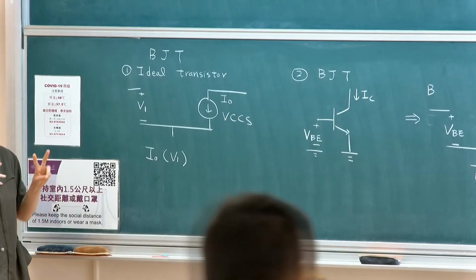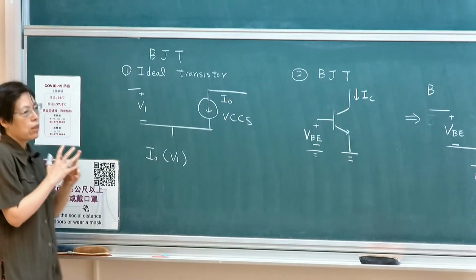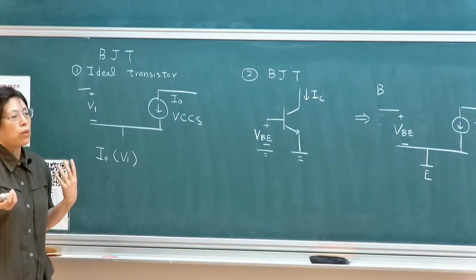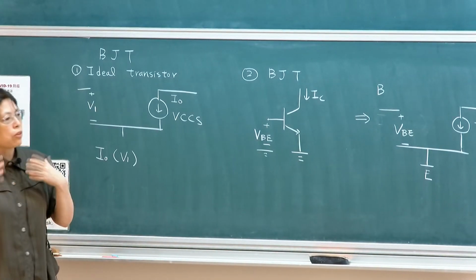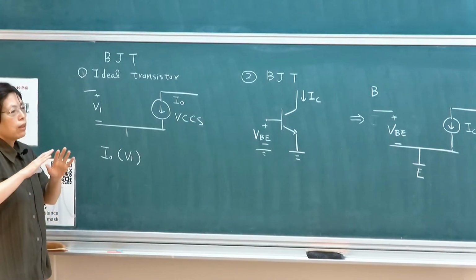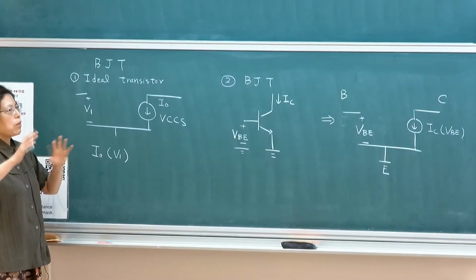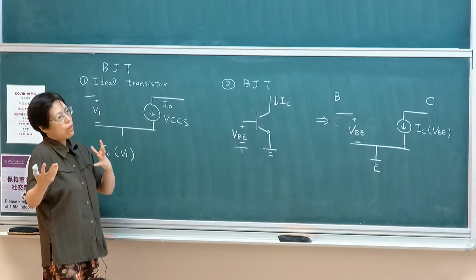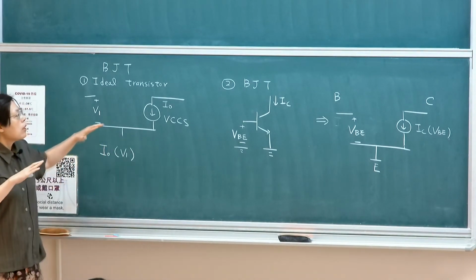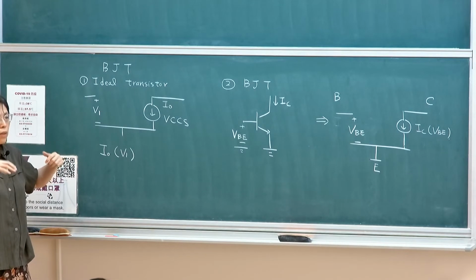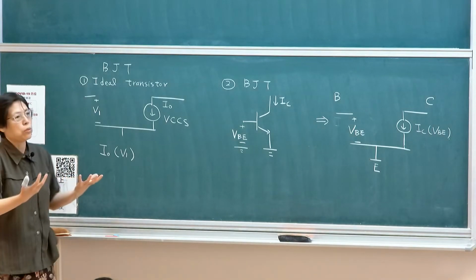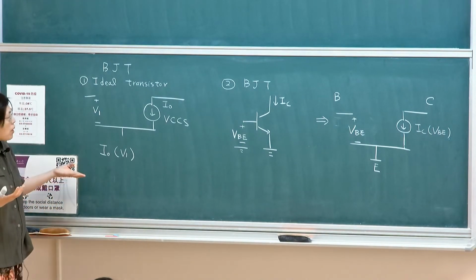As I said, for a transistor, there are basically two functions. One is, for digital circuits, the switch. You think about whether it's on or off, whether you want to turn it on or turn it off. So you're basically operating in two modes: you turn it off, or you turn it on in a saturated mode. The basic idea of a switch is that when it's off, it blocks the current or the voltage, and when it's on, it allows the current to flow.